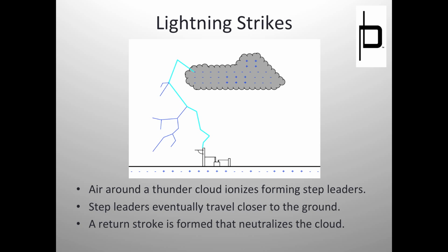Well, and again, in some cases, it's based on current flow, which is current flowing up or down. Generally speaking, most lightning strikes form because of a negative charge on the cloud, but it can be the opposite. It can be a positive charge on the cloud looking for negative. So when we talk about up or down, we're talking about current flow. But generally speaking, the return stroke is current going from the ground back up into the cloud. So your positive charge is going back up into the cloud. Right. So that's how that bright bolt is formed, and that is the muscle of the lightning stroke. That's the bright flash that you see, and that is the heavy current that's very dangerous, and it occurs over a very short amount of time.